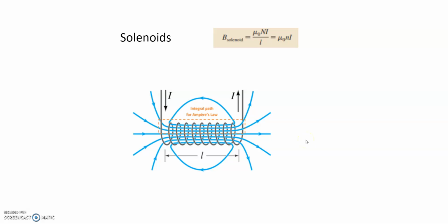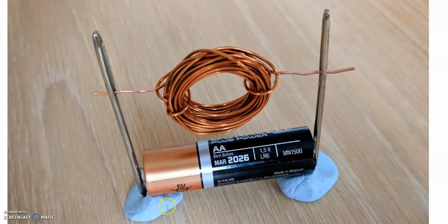And then this can be used to create even more interesting technology like electric motors. Electric motors actually do this same thing. This picture right here is a very simple electric motor. I highly recommend you do this at home if you have never done this or never seen this. Basically, how motors work in their most simple form is, this wiring here has some insulation on it. If you look really closely, you can see that half of it is shaved off on one side, but the other side is not.